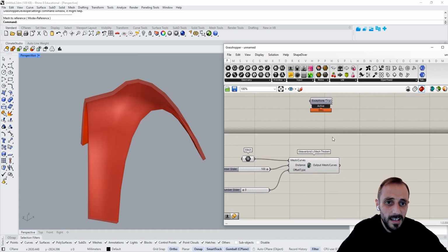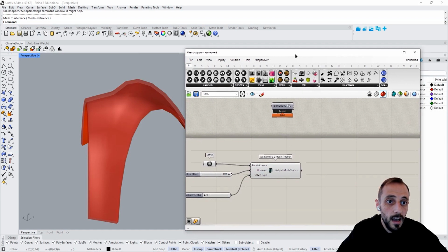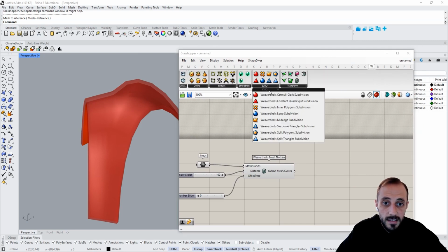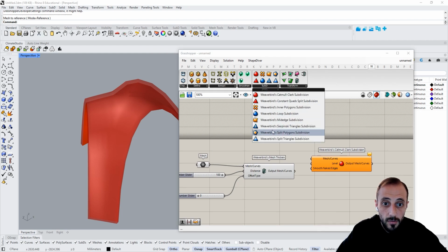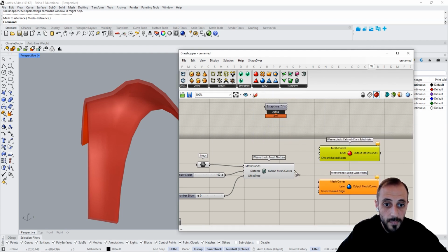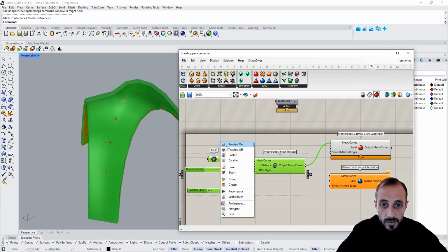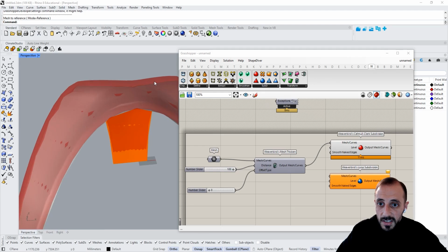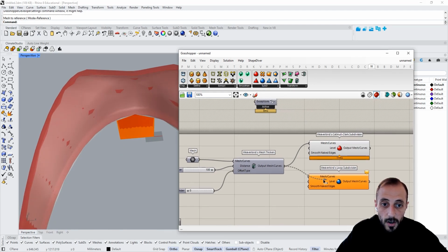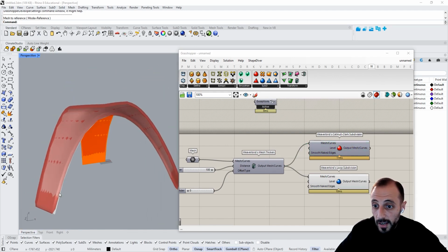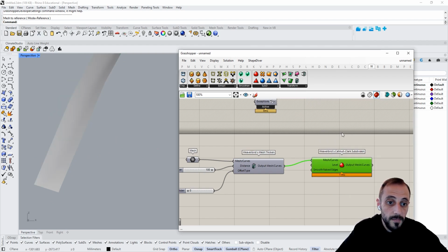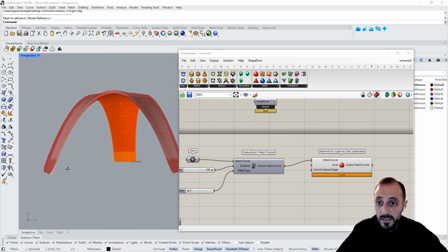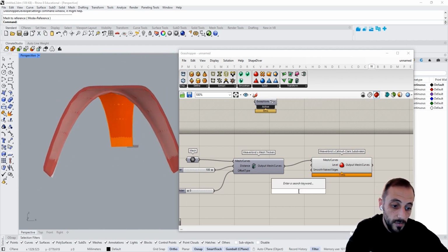And the next thing that I'll be doing in the Weaverbird, again, I'll be smoothing this structure. So I can go with Catmull-Clark Subdivision, or I can go with Loop Subdivision. So let's preview this all off, and you started to see we started to get this or this one. So again, whichever one you like, you can go with that. I'll go with the Clark Subdivision, and when we increase the level, we'll see smoother results.